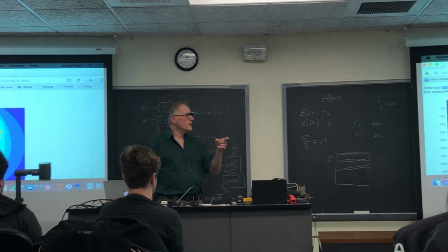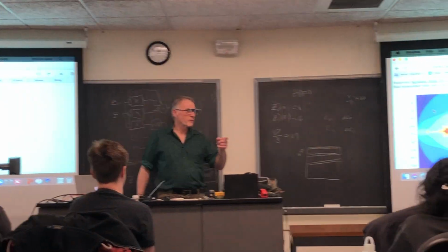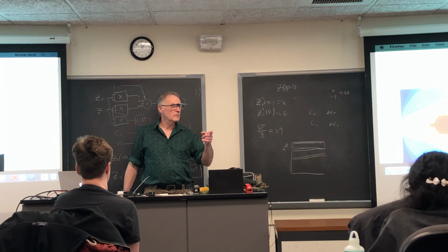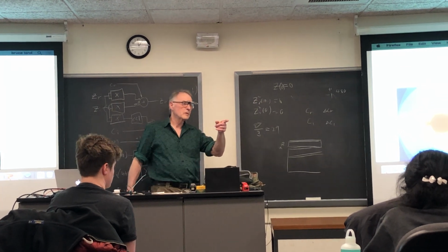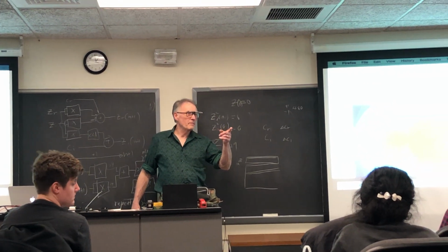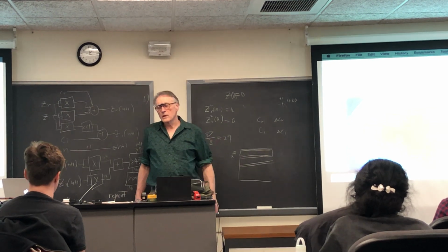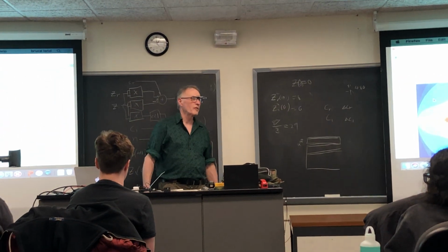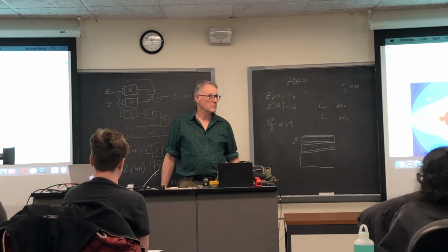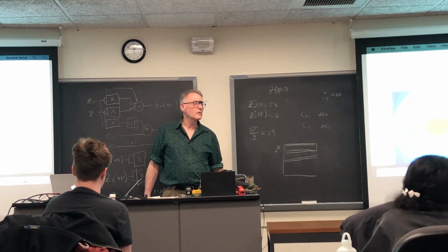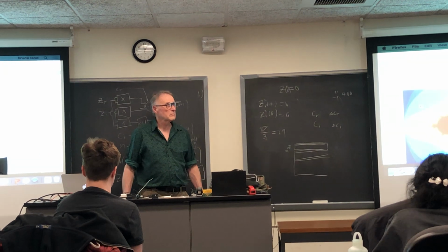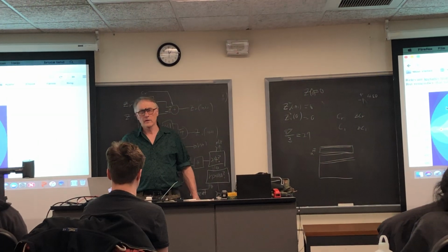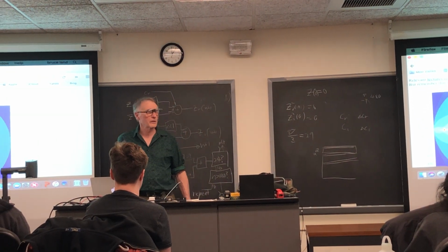Somebody was using this strange construction, dollar readmemh or something like that. Or using, what was it called? Dollar readmem. So what, I looked it up, what Quartus does with dollar readmem is it generates a memory image file for you and makes a ROM. So that's one way of making a ROM easily, without having to figure out how to make a memory image file.